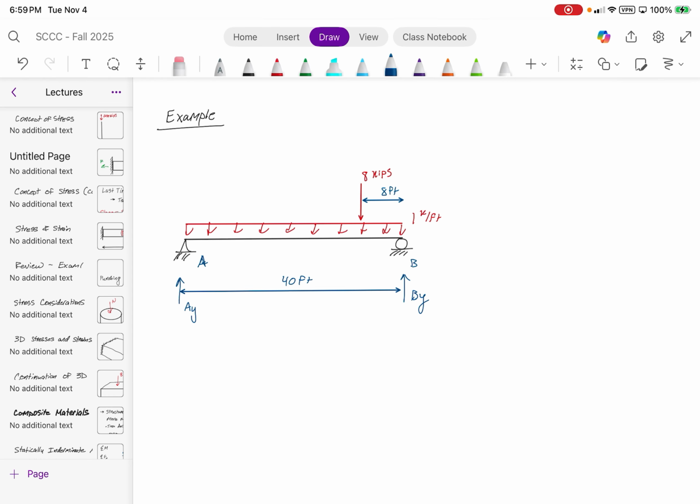Otherwise, my recommendation is, what is that shear right there, at that point? Negative 18.4. All right, so take the average between those 2 points and then multiply it by whatever span length this is, because that'll give you the same. Then add that to the existing moment that you calculated for that point. And it should close out to 0 if you did it right. Okay.